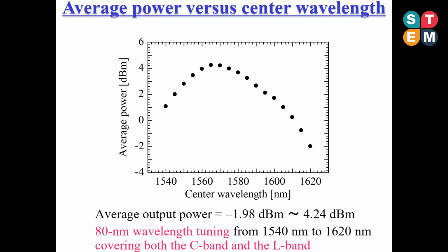The wavelength dependence of the output power is mainly attributed to the gain profile of the bismuth-based nonlinear erbium doped fiber. Therefore, the output power can be increased, and the tuning range can also be broadened if we use pump lasers with higher output power.